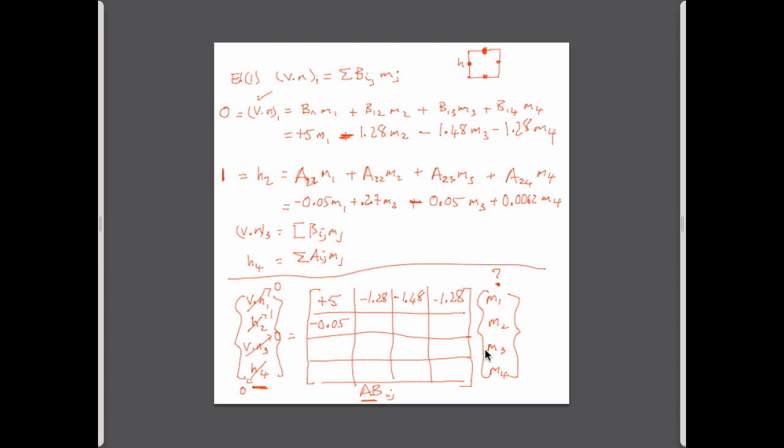So now we do the converse. We go back and we can write the equations exactly the same as we did here, but now at this top surface, instead of wanting to solve for the value of the velocity, which we know as a boundary condition, we'd like to know what the head is. And so instead of writing the equations in terms of this at element 1, we'll write it in terms of the influence that gives us the head at that point.